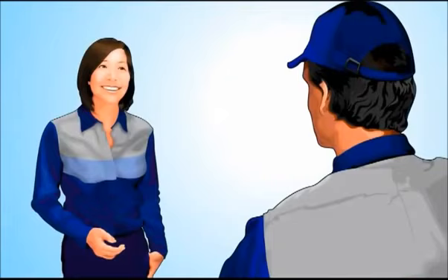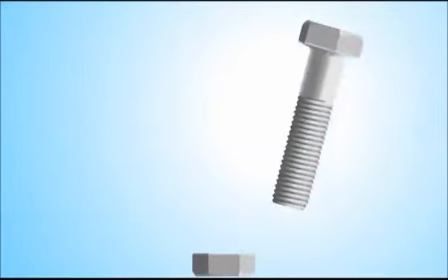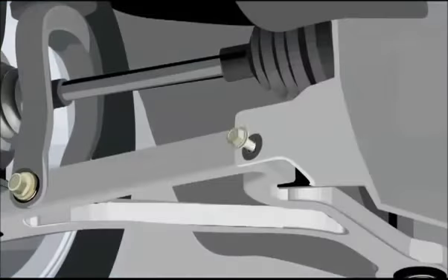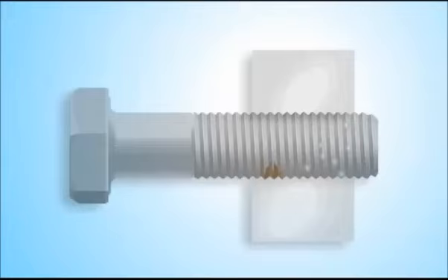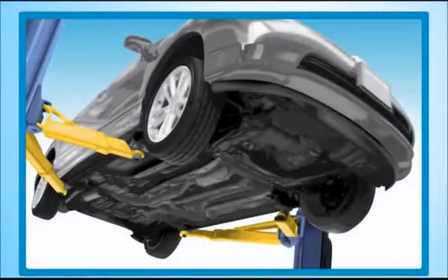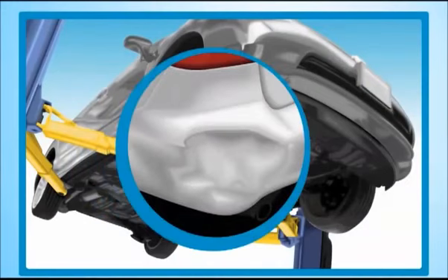You may run into situations where fasteners are damaged and require repair or replacement. A few reasons for this are cross-threaded fasteners, over-torqued fasteners, the wrong fastener being used, the fastener is corroded, or it failed due to outside influences such as a collision.